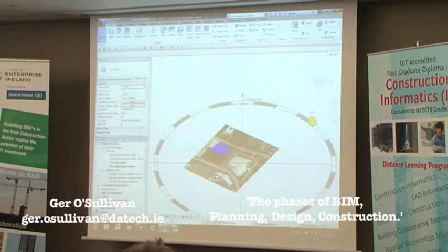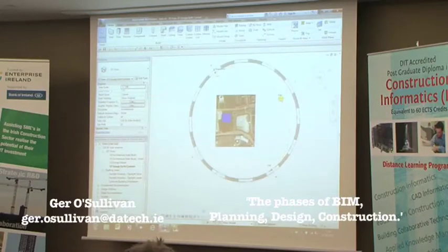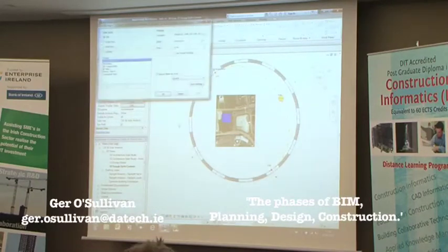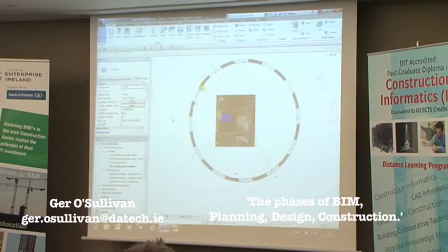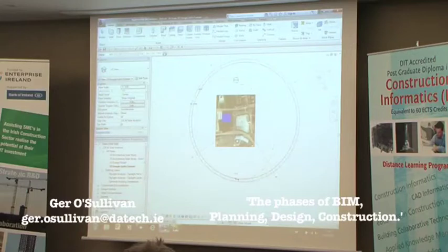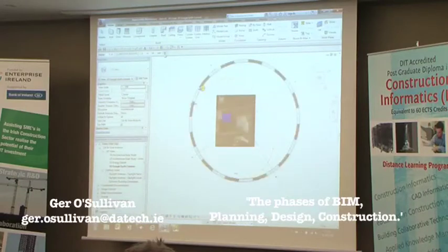Or you can actually animate it. I'd probably like to do it this way, so I might go into a top view like that, and we'll change our sun settings from, say, a still to a single day, and we'll play it through. When we play the animation, we're actually going to see the shadows animated. And obviously, if that affects any of the nearby buildings, you're going to see that updated on the screen. So again, very slight shadowing, but you get the idea.